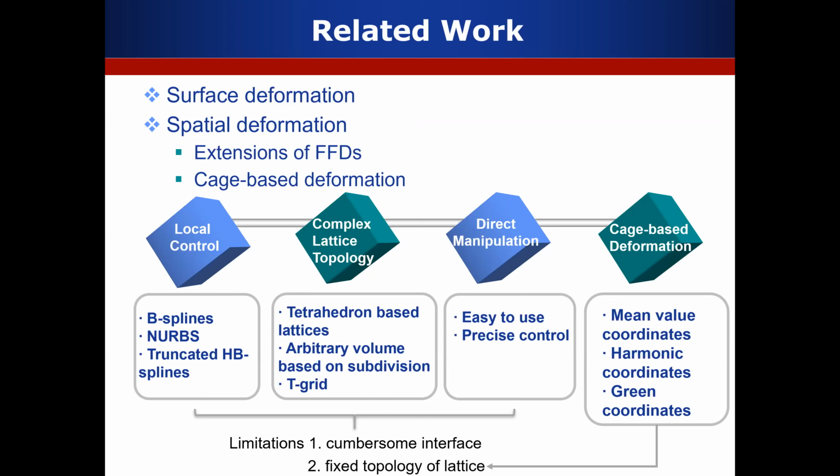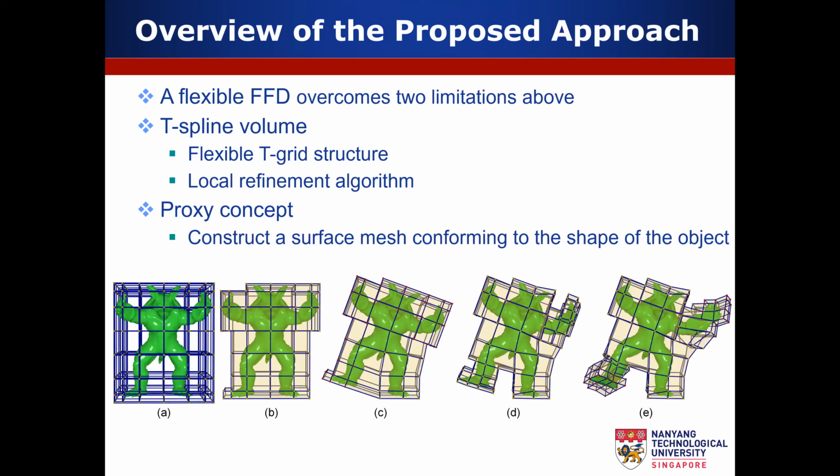It was also worth pointing out that our paper does not aim to improve cage-based method, though they do not allow topology change of the cage either. So in this work, we present a flexible freeform deformation method that overcomes the two limitations of many FFD methods. The underlying core technique here is T-spline volume.